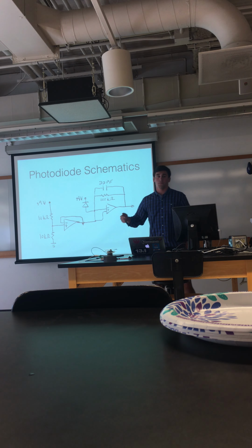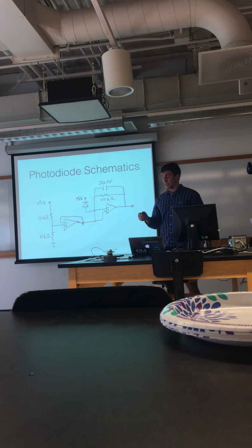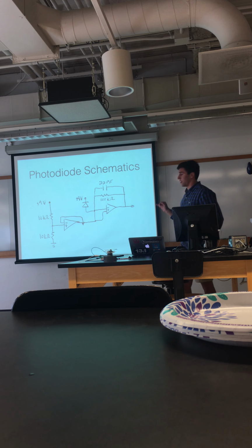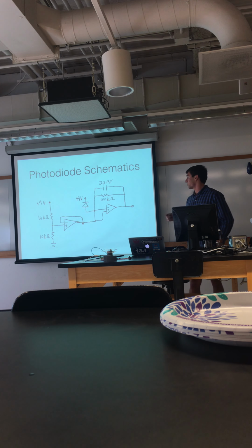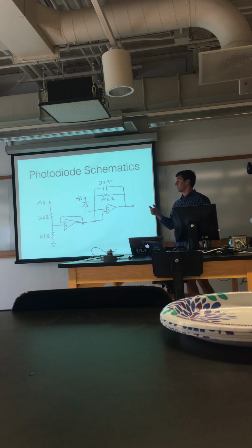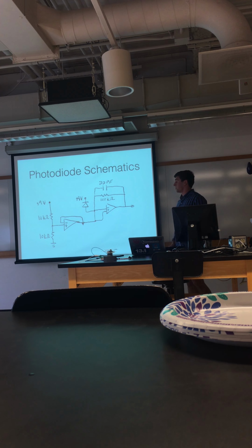And then another problem that I ran into when we were doing this is that this created a lot of oscillation. So the photodiode itself oscillated a lot on the oscilloscope. So that 22 picofarad capacitor just cuts down on the oscillations.